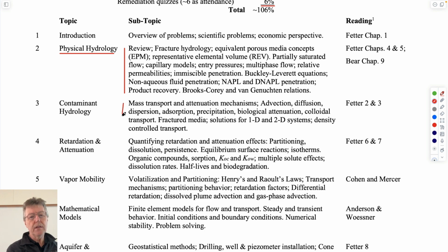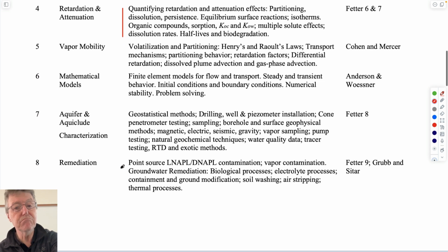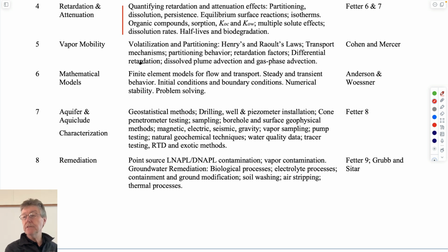We'll talk about when they get to a location where they don't move anymore, how diffusion occurs, and that the contaminants will diffuse with the help of the water that they're dissolving into, how they might attach onto the solid substrates of the grains of soil in the subsurface and be diluted as a result of that sorption, and be attenuated as a result of that.